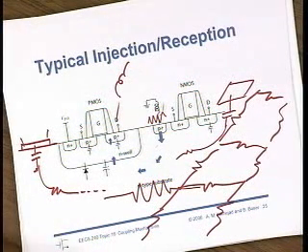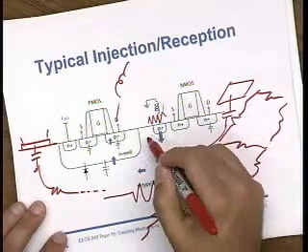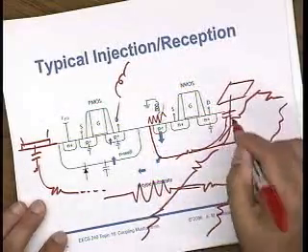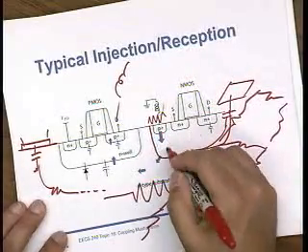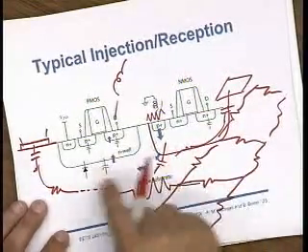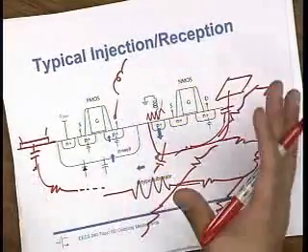So nowadays people start using like the triple well or the additional well to decouple two sensitive parts. Yeah, it helps, right? It helps. So what happens is that now, instead of having this ohmic contact, I have to go through another capacitance. But it's still there, right? This might buy me 20 dB or something, but ultimately that coupling is still there.